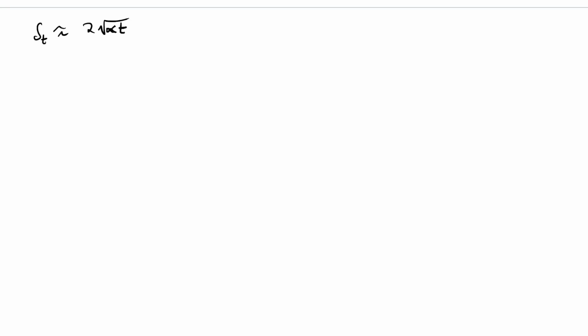But we have this t component here, and we don't have a transient problem. There is no time. This is a steady state problem for sure. So we have to introduce something that represents time. So how do we represent time? Well, time is just equal to the position x divided by the free stream velocity u infinity, right? So we have meters divided by meters per second. That gives us seconds, right? So our time here is this.